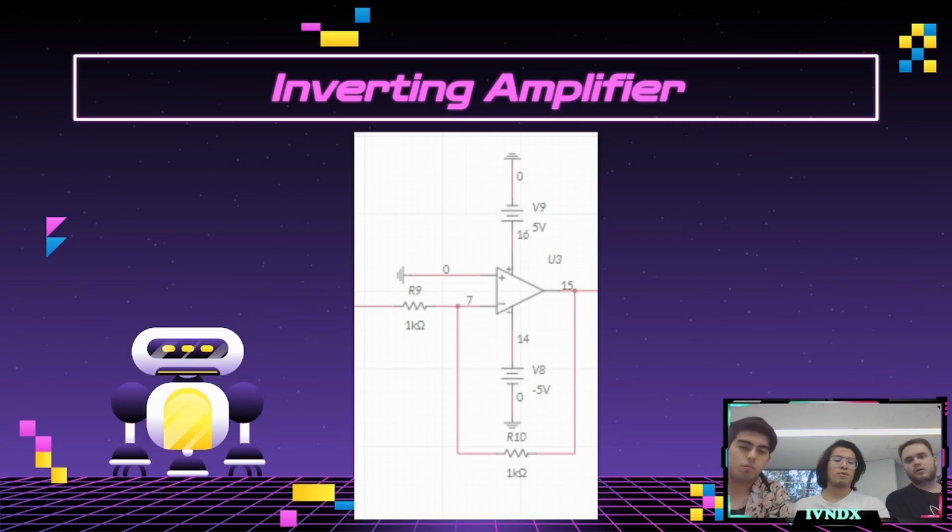So, as Ivan said, our solution here is basically making an inverting amplifier. It essentially takes 5 volts and turns the signal upside down, and then gets another 5 volts out, maximum and minimum.